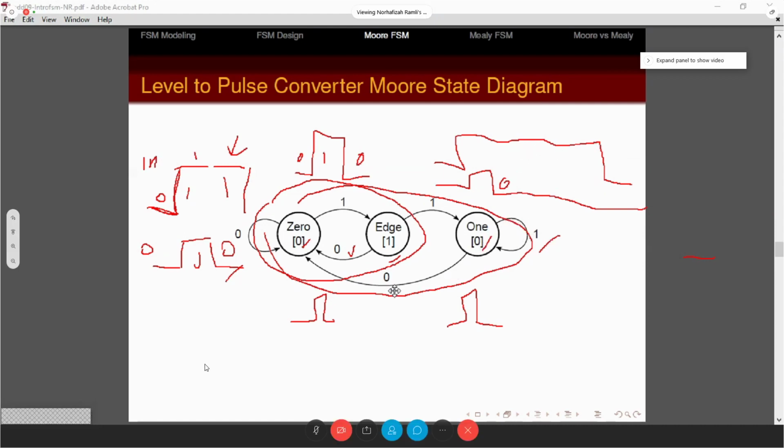But if you start receiving 0 here, then obviously if you see 0, the next thing you expect is 1. So that's why it has to go back to the first, the 0 state, so that you can start looking for the rising edge. That's why you need the third one. For a detector like this, you detect 0, 1, kind of like you detect two sequence. You have to detect 0 and 1. That's why you need 1, 2, and you need the third one to settle.